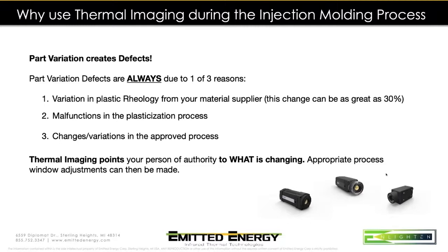Now I can make five different turns, or I can tell myself, okay, I've got a thicker or thinner plastic. And if it's a thinner plastic, then the easiest way to make one adjustment and keep it simple when I have varying plastic going on, if it's not shear related, is to just change my melt temperature and lower my heats all at once and just watch that temperature and see what happens.